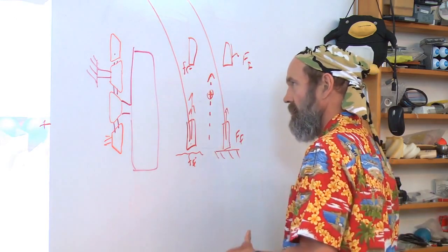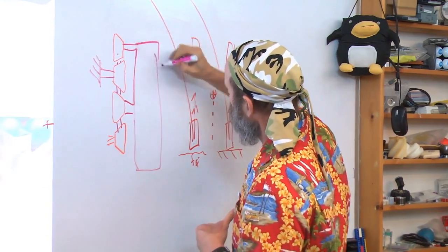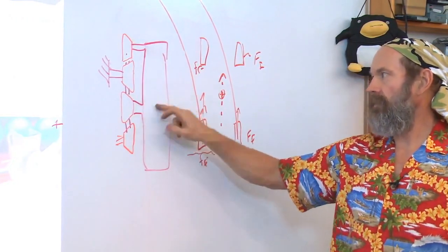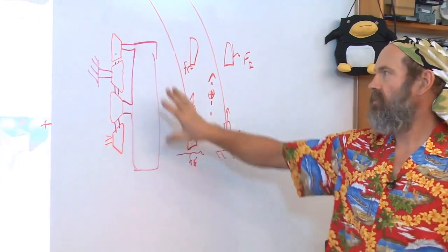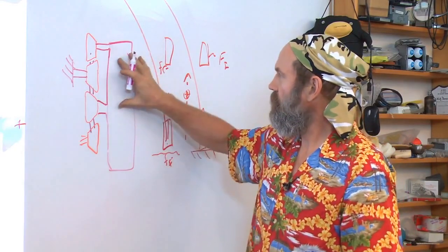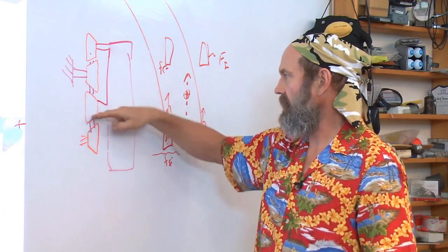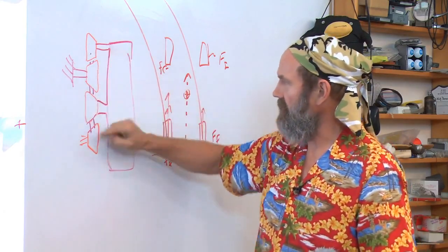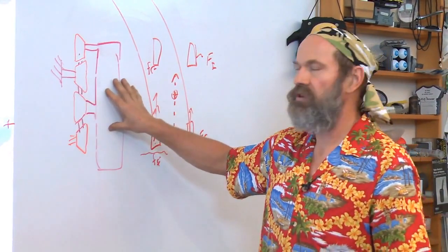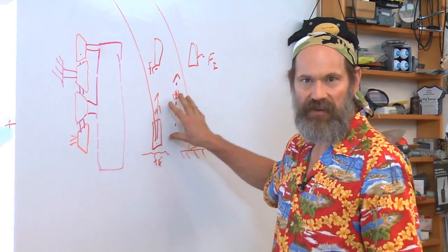And what happens now when weight comes down? What happens to this door? Remember, this is a surface of revolution here. The weight of the door comes down this angle, wedge engages that angle, and it wants to slide down. And it can't go that way linearly because of the hinge pin in the middle, so it wants to rotate around. Whoop, and the door closes automatically under its own weight using the principle of self-help.